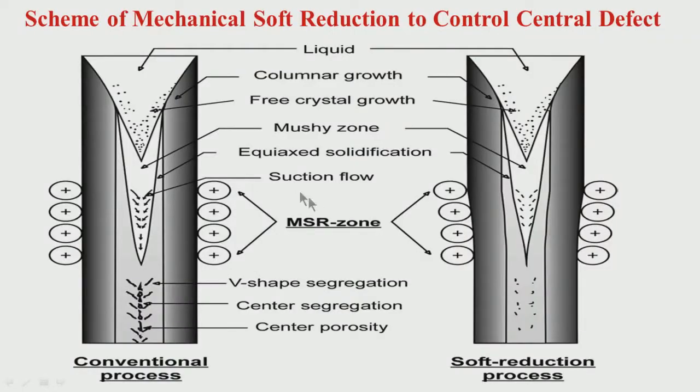You may have manganese, you may have some silicon, you will have some amount of other alloying elements, you may have titanium, a small amount of chromium, a small amount of molybdenum, a small amount of nickel. So for all these elements there is a possibility of some segregation, and as I have told you, the amount of segregation is more towards the end of the solidification.